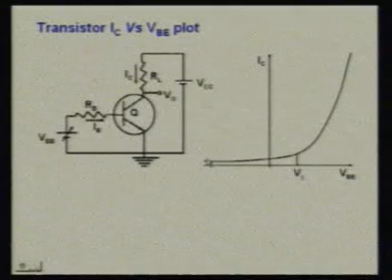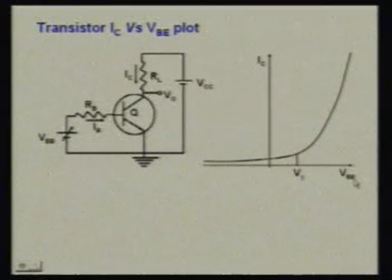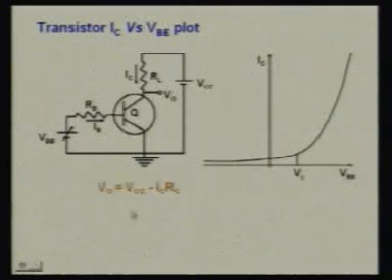So this is the characteristic curve. We have plotted VBE on the x-axis and IC on the y-axis. Here the axes are not scaled. So here again we see that if we increase VBE, that is the voltage between base to emitter, then we find a very small current IC through the collector, and when VBE is greater than some particular value, again we will say V gamma or cut-in voltage, again current increases very sharply. So we have taken V out at the collector junction.